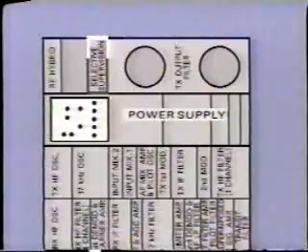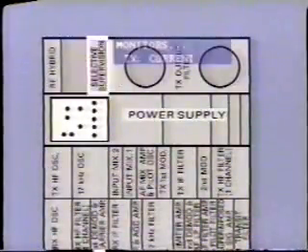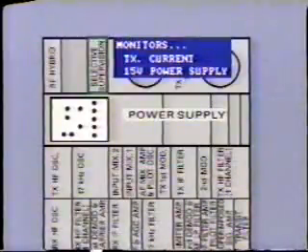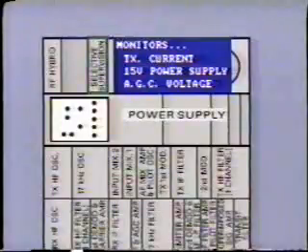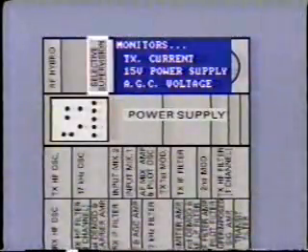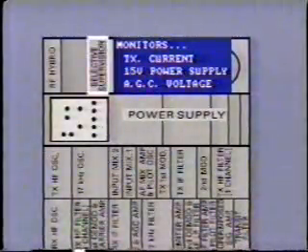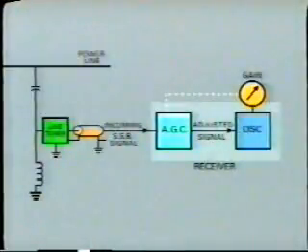The next module in the panel is the supervision unit. It monitors three things: the transmitter current, the 15-volt power supply voltage, and the receiver's automatic gain control, or AGC, voltage. When the incoming signal is strong, the AGC turns down the amplification or gain of the input signal.